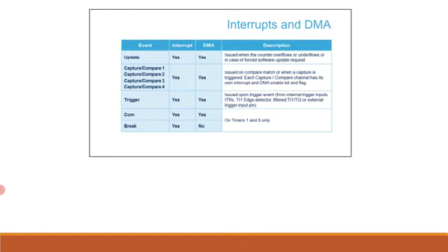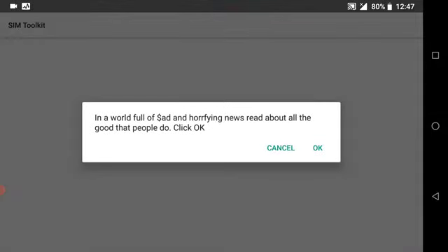The repetition counter allows you to skip some PWM periods and decrease the number of interrupts or DMA requests at high PWM frequency. Each of the 4 capture or compare events have their own interrupt and DMA. A triggered event on TRGI input, regardless of trigger source, can also trigger an interrupt or DMA request.